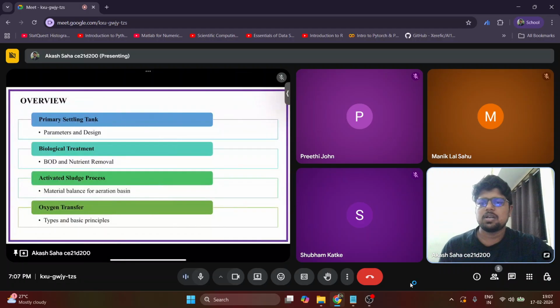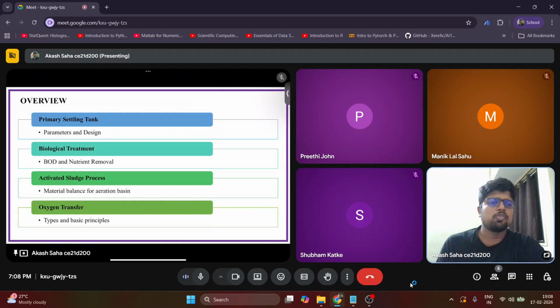So anyway, let's have a quick overlook of the week 4 contents. In week 4, we started discussing the primary settling tank, where we learned about the various parameters and how to design a primary settling tank. And then we moved on to the discussion about biological treatment. So what is BOD and how to remove it. Similarly the case for nutrients.